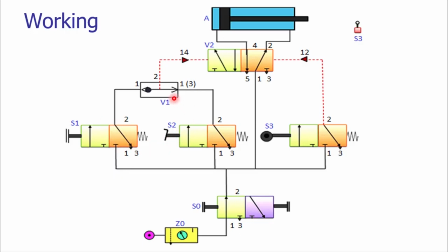So instead of blocking the foot pedal valve, now there would be blockage of the push button valve. The ball will move from right to left direction and the push button valve will be blocked, and the compressed air will be given to the DCV via the shuttle valve.